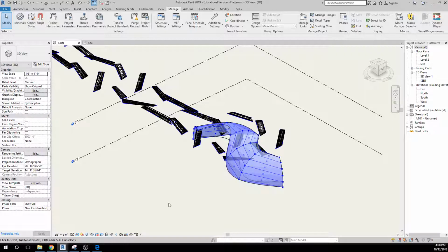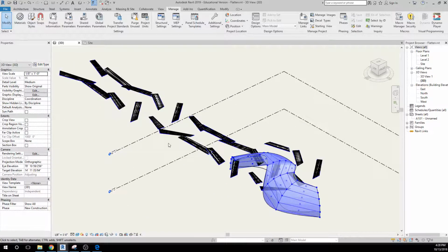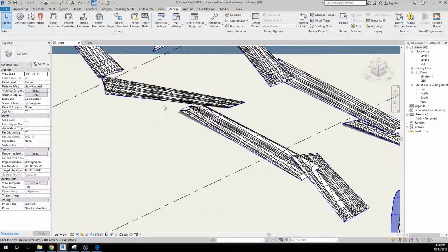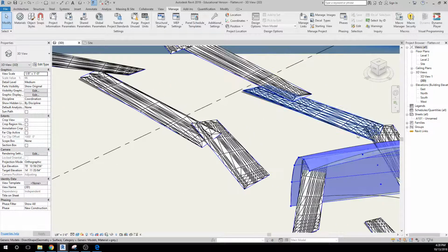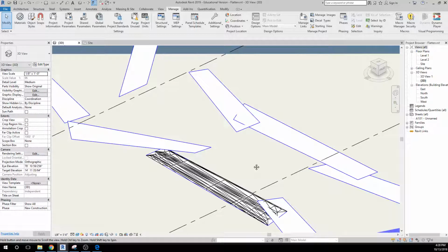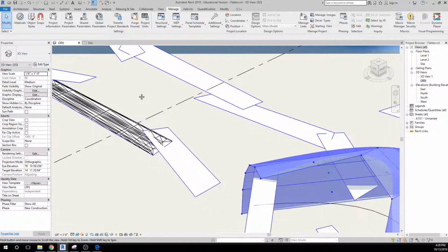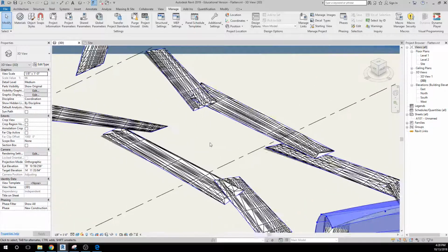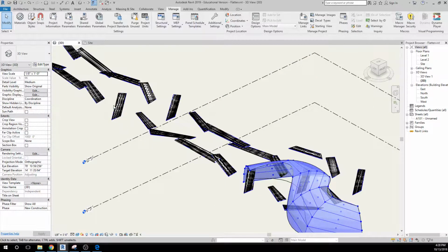And then in the Dynamo, we're actually taking these surfaces and laying them flat on the plane so that we could actually create either tooling paths or construction documents about what each panel shape is. What's interesting to note here is these panels aren't lying perfectly flat. You can see a little shadow detail under them, even where one lays over the top of the other. And that's because these aren't planar. They actually have a twist to them to better conform to the shape. And we'll look at the difference between using panels that are 4-sided to 3-sided ones, and how we can get those 3-sided panels to look perfectly flat.